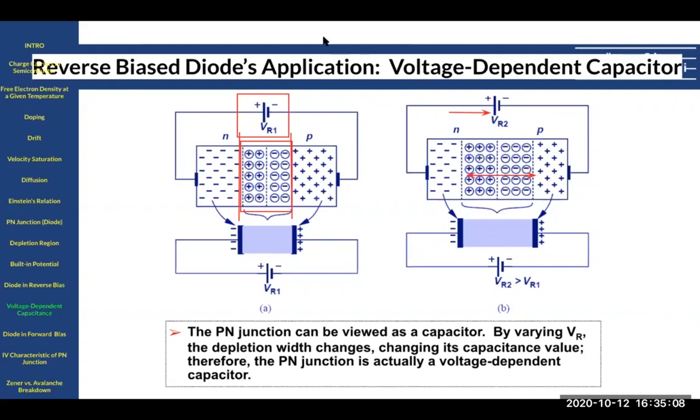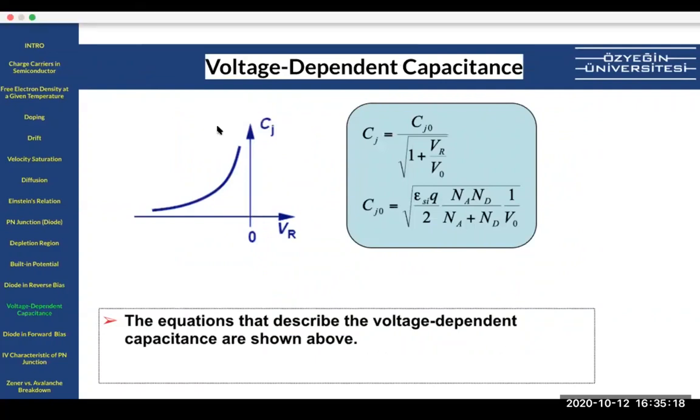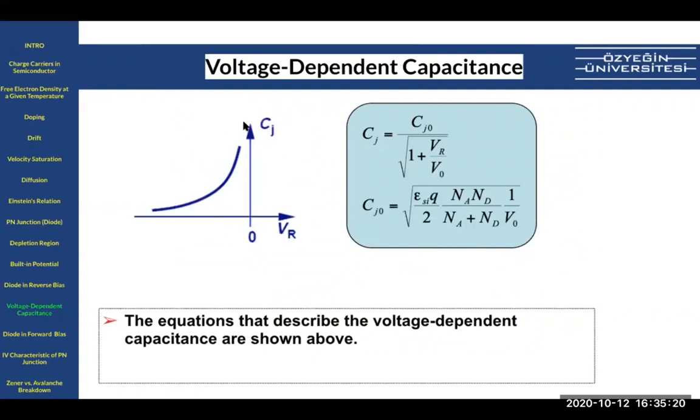So what happens is the characteristics of an integrated circuit capacitance, just like this. You have a zero potential voltage and you have a fixed depletion region. And then you start to increase your reverse bias. You start to increase the absolute voltage in the circuits. And when you start to increase, the depletion region starts to increase. And as you can see, the capacitance goes down.